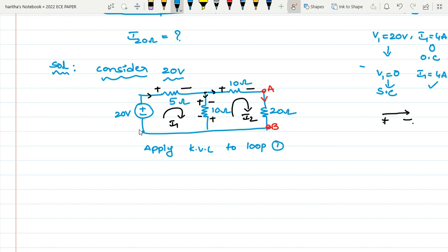See, in this also you can take two methods. First, when I'm tracing my path, whatever first sign I am seeing, I will take that sign, or else the leaving sign also you can take. See here, the current is entering positive potential, right? Or the current is leaving at minus potential. So you can take either positive or negative.